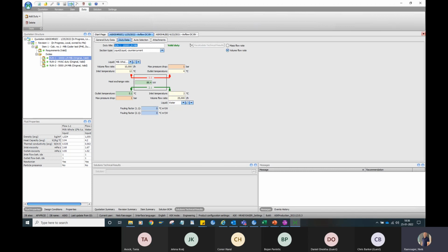As an example, when we are dealing with fatty products, we say maximum 1.5 up to 2.5 meters per second in the fitting and in the port, in order not to disturb the fat globules of the product if we go higher in velocity. But the program is designed for industrial, so it actually allows you to go up to 6 meters per second.